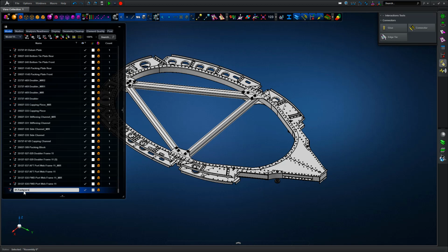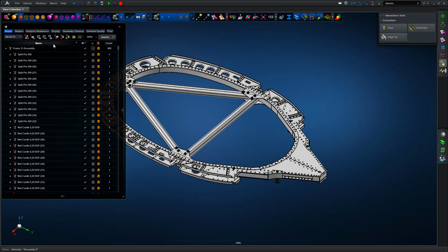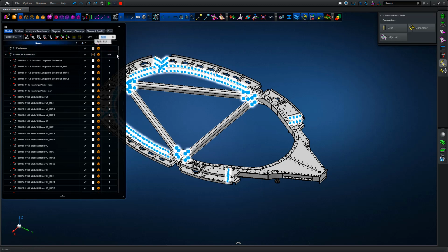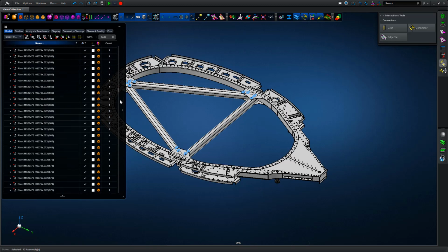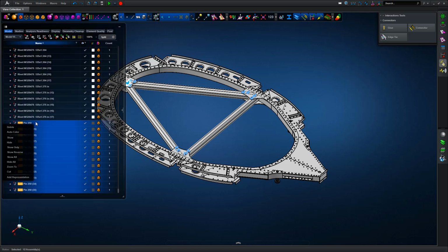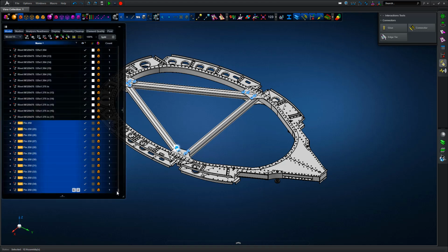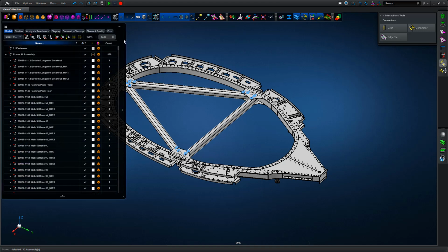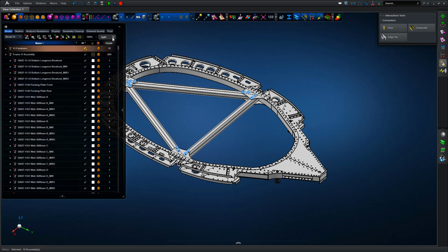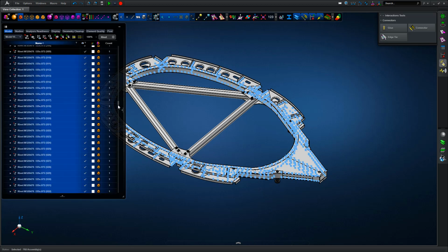We're calling it fasteners. So we're going to ultimately take out all of the redundant fastener definition for this first level model and just leave us with the structural entities. So based on the search string, we've got lots of split pins first of all. Using a split term within the search string, we can cut those entities out of the original assembly and then paste them into the fastener container subassembly to simplify the model.